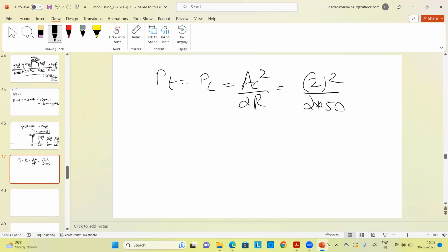So now I have a question. Why are they asking to measure the 98% power bandwidth of the FM signal? See, here they're talking in terms of a practical aspect. Even when we generally say bandwidth, it cannot be a completely ideal bandwidth.